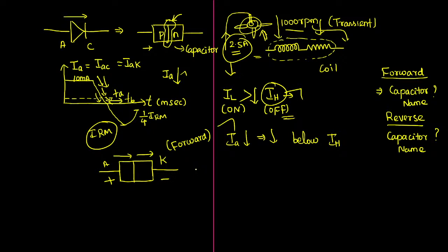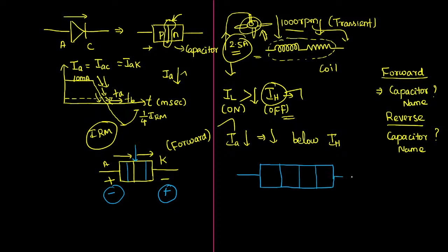Okay, fine sir. Now what I'm going to do is reverse the polarity across the diode. What will happen? It may be an SCR also. If I reverse the polarity for the SCR, you can add one more terminal such that it will produce the properties of the SCR. That's all. This is the SCR now. When you reverse the polarity, I am injecting positive voltage here and negative voltage here. Let me explore elaborately. If you look at the SCR deeply, you might have observed there are 3 junctions inside the SCR: 1, 2, 3. Yes sir, there are 3 junctions.